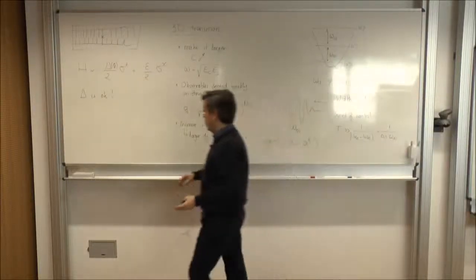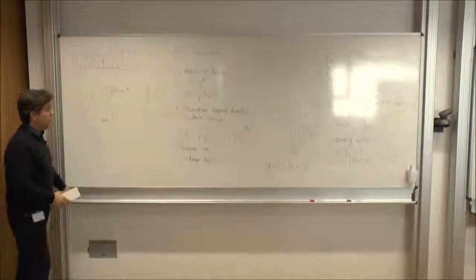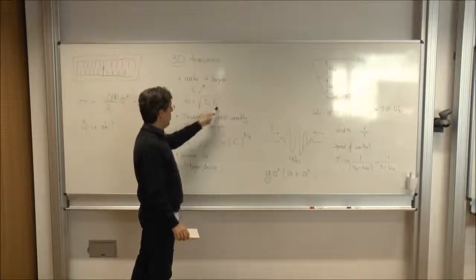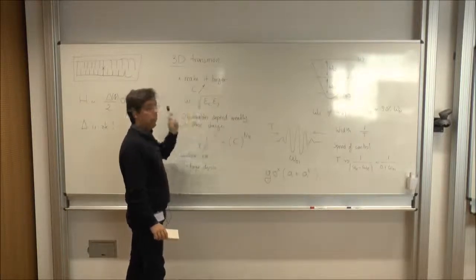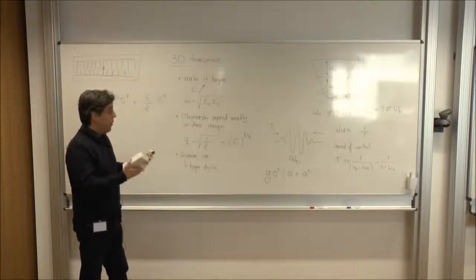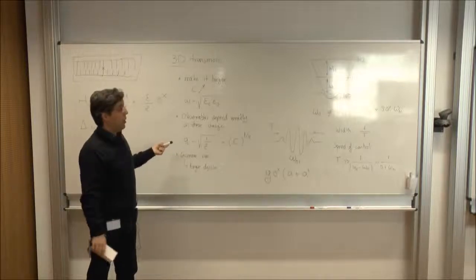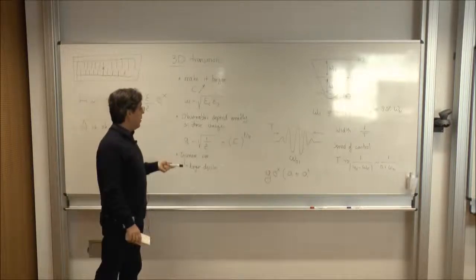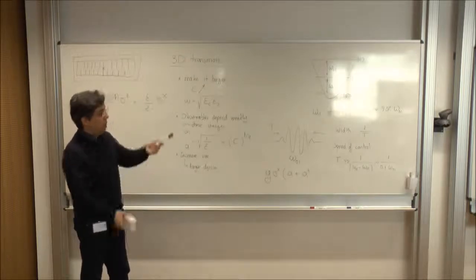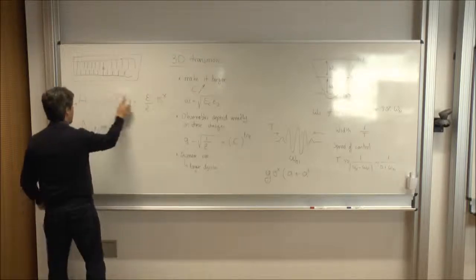And well, these 2 ingredients. The transmon by itself is a very good qubit, which is very reproducible because the frequencies depend very weakly on the fabrication items, like capacitance that can be engineered geometrically, or the Josephson energy. So it's very robust in terms of reproducibility. It couples sufficiently weakly to the environment. It has low decoherence, and now if you put it in an environment that really isolates it better, then you would have a long lifetime.